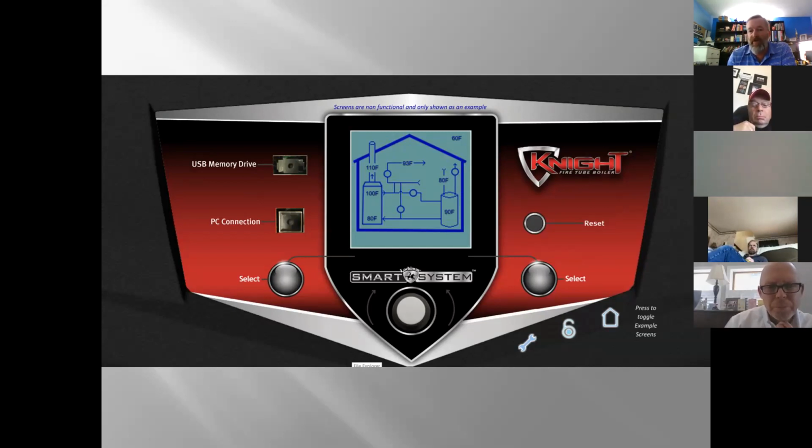So a lot of times if you're troubleshooting, you want to know what's going on, go to this screen first. If you're like, hey, my water temperature is not warm enough, and you're like, it's 30 degrees out, you look at this screen and it says it's 60 up here, you know you got a problem with where that outdoor sensor is reading. And the electrician might have done a really good job of getting it in a nice, sunny, warm spot. So definitely want to take a look at that.